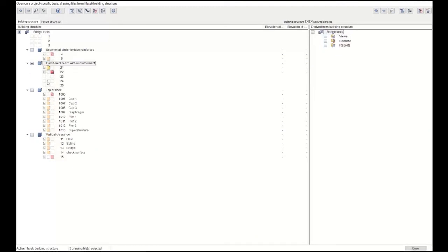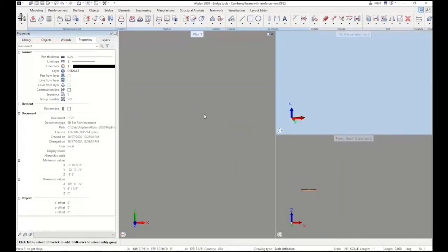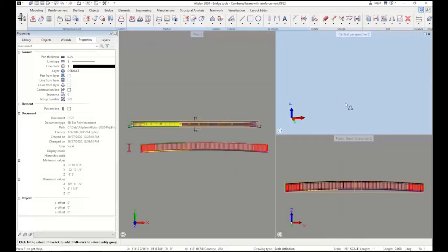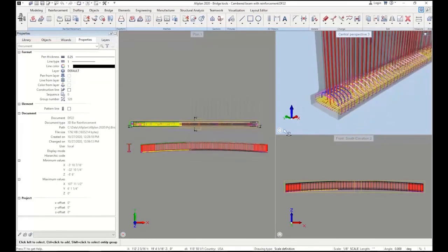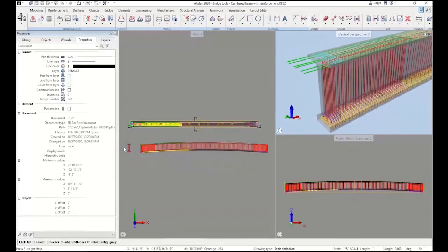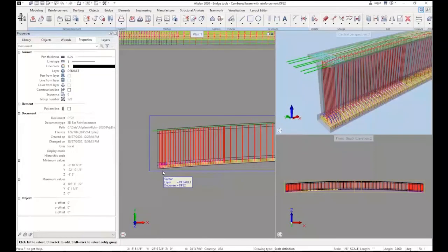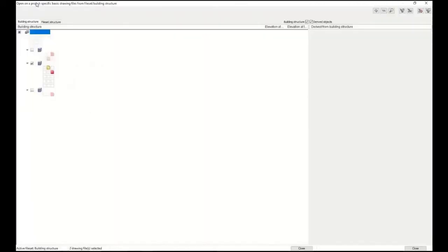All right, next we're going to look at that sweep bars along path, this time for a cambered beam that you may have in the kind of bridge we just saw. You know, it'd be a very small camber though, it'd be hard to see. So I've exaggerated this a little bit. It's got a 2-foot camber over 100 foot here, but we can quickly see that I was easily able to select bars in my section and now place those bars, and I have the tighter spacing here at the end with the higher shear. I can do projecting bars if I need to for my restraining moments, or to create them continuous for live load. So it provides all that flexibility that you need.